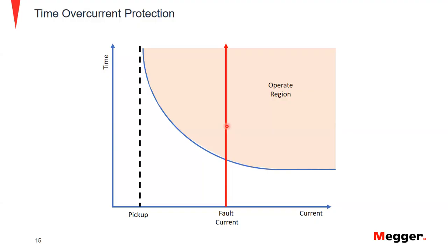The operations usually happen right on the line, with the plus or minus percentage listed by the relay manufacturer as well. If we were to try to capture this time, as we're testing we will provide specific current multiples along this graph to allow us to see the difference in time. As you can see, the least amount of current will provide us a longer time, and the higher amount of current will provide us a shorter amount of time, which makes it an inverse style curve.